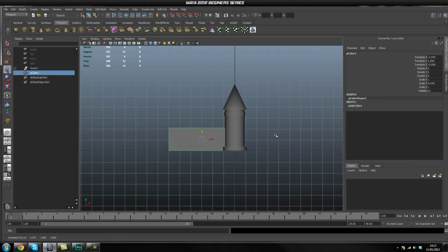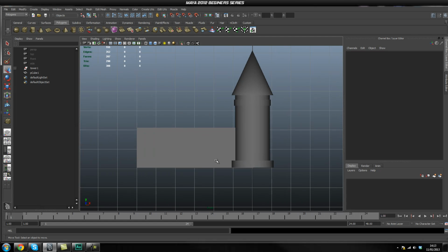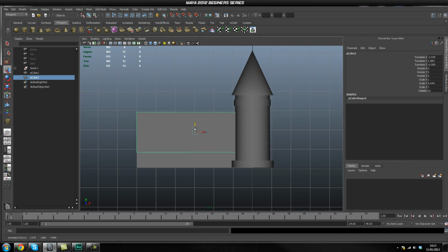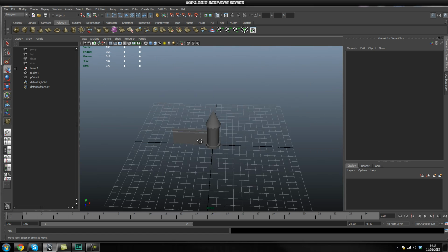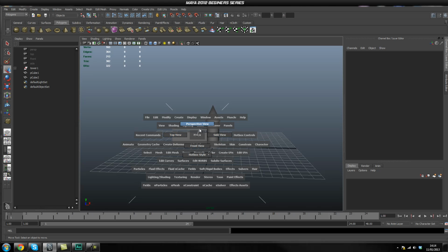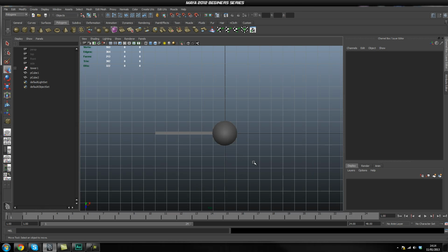So now that I got my wall created, it's looking amazing, but it's a bit too boring for me, so we're going to make it a little bit better. So if you select your wall again and press Control D to duplicate, and we're also going to scale this down really small like so, and then we're going to move it back up like so. So this will be the top, we'll have some pipes coming down here in between that supports that top bit.